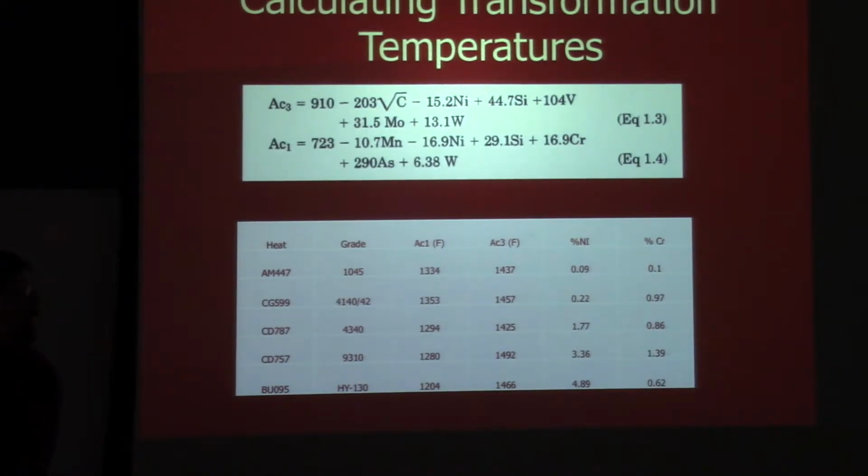But nickel, we put it in at 3% or more sometimes, because nickel has the unique, I shouldn't say unique, but certainly the significant role of improving toughness. So when you're making engineering components, toughness is quite important. It also has a significant benefit on what we call hardenability, which we will get into later in the lecture. So I'm not going to cover it right now, but it is a very necessary element in a lot of things, and so that's why I kind of picked up on that one.